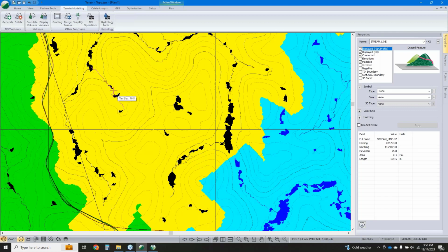Awesome. Let's keep talking about hydrology for a second. If someone has already calculated their hydrology in another software, can they load that in and leverage it in Path Explorer? Yeah, totally. Doesn't have to be features that come from RoadEng. It's just a polyline. If you bring it in as a shape or a DXF or DWG or DGN, etc., it's still going to just be a terrain feature once it's in terrain, and you can apply whatever you'd like to it.